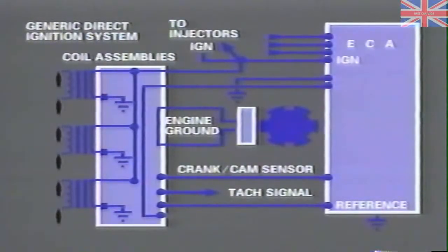In place of the typical distributor, a camshaft position sensor is utilized that contains a Hall effect sensor. It operates similar to a profile ignition pickup assembly that you are familiar with. The cam sensor's output, in conjunction with the ignition control module, operates with the EEC-4 computer system the way it always has.